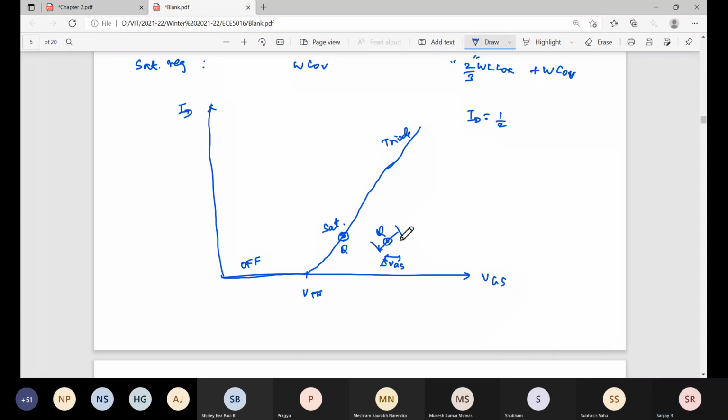Am I right? From a very small perspective, the line looks linear, such that the variation in VGS is a very small signal. That means I can operate the amplifier in a linear region, applying a very small signal, so there won't be any non-linearity. We are always interested in studying the behavior of an amplifier in the linear region, so there won't be any non-linear distortion.